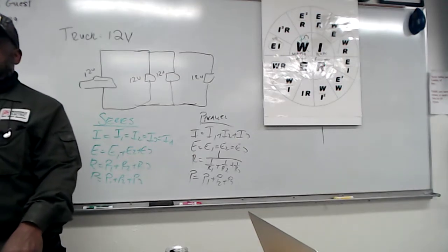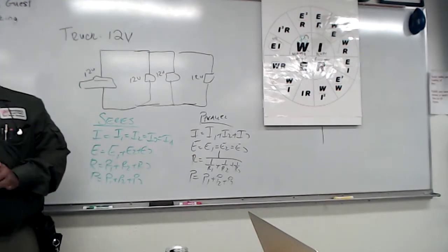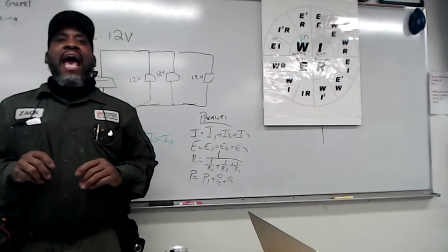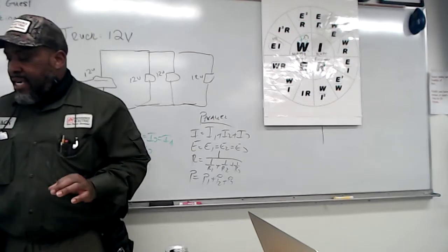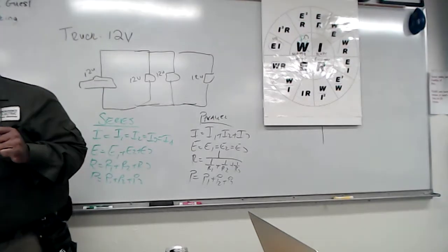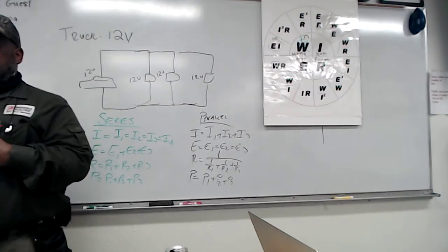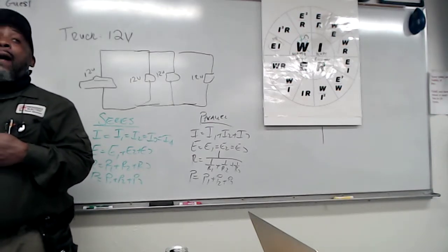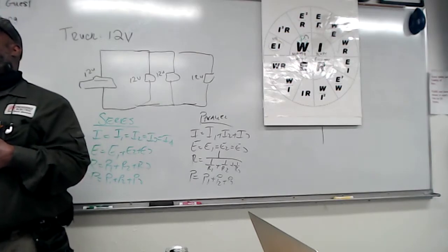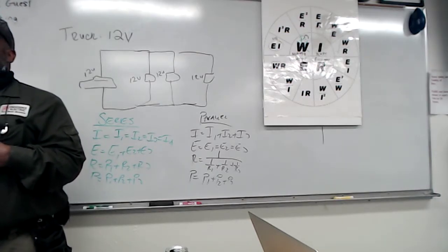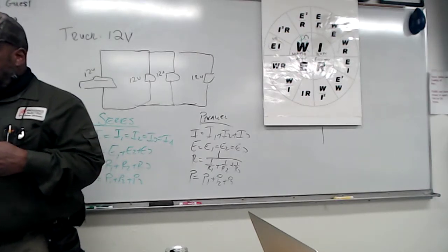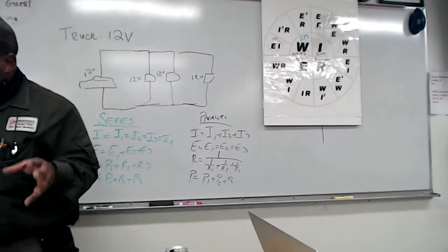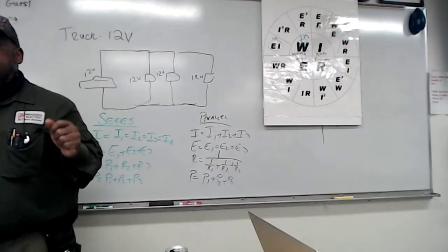But the problem is this table, 310.16. What is this table rated at? Read the top of this table. You should highlight this. I got mine highlighted. It says Table 310.16, Ampacities of insulated conductors with not more than 3 current-carrying conductors in a raceway.